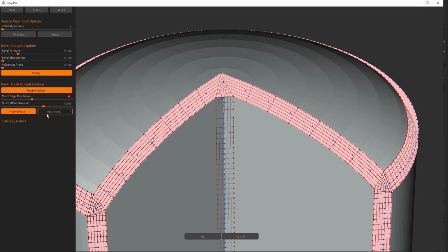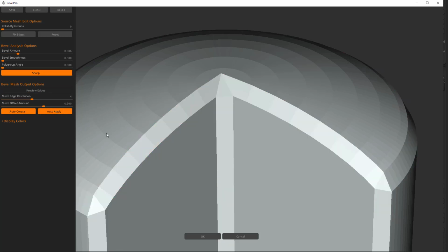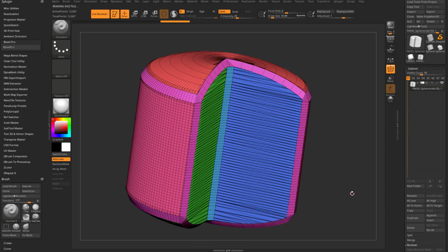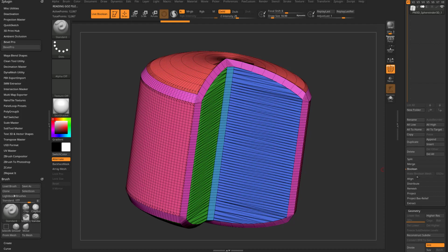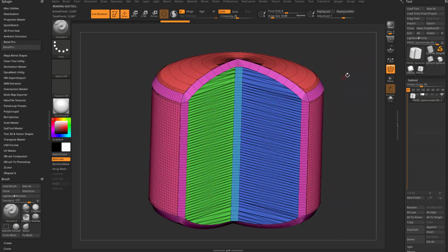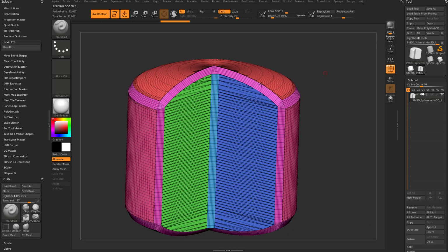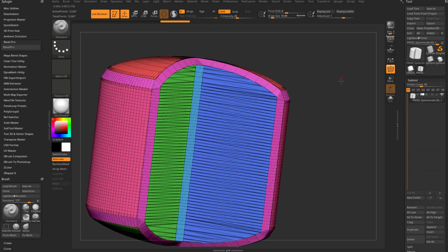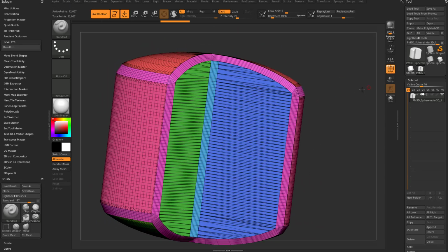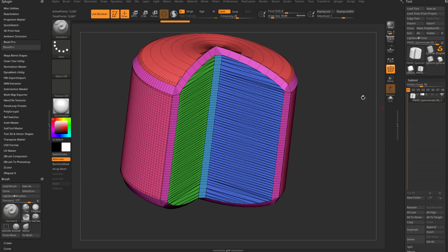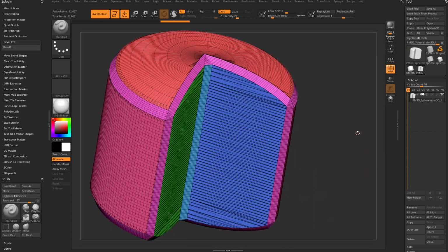We have mesh preview turned on, and this time we're going to turn on auto apply. So when we have this button on and we hit OK, instead of having to do what we did previously, which was make Boolean mesh, this one does it for you. It's a little more destructive. It's basically sitting here already Booleaned and already run, but if you're not looking to keep those other meshes around, this might be the better option for you.